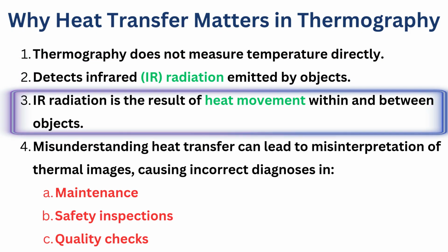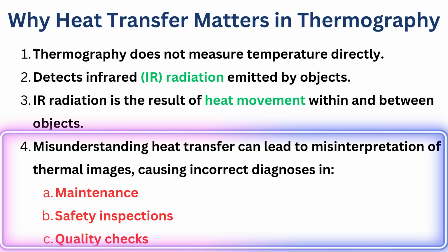Overall, this radiation is the result of how heat is moving within the object, or between the object and your infrared camera. So it becomes very important to know about these principles, otherwise this can lead to wrong interpretation, or wrong diagnosis of the fault.